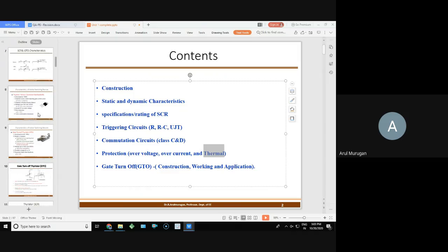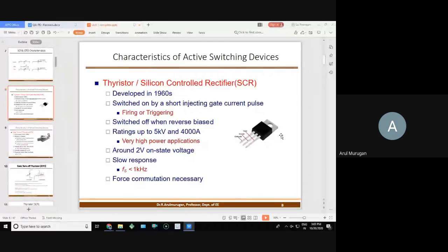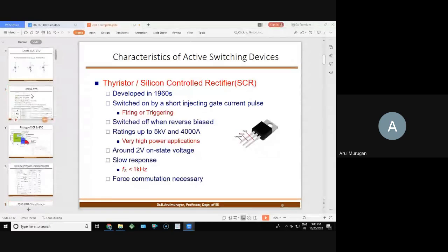That is the device. The base at the back is connected to the aluminum heat sink, through heat sink paste and a mica sheet. With the help of the mica sheet and the heat sink, it will absorb the heat and reduce the thermal heat. Okay, that is a heat sink.